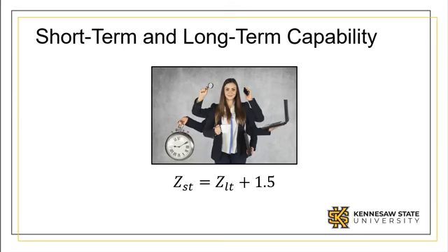Processes are typically assessed based on one operator on one shift, with one piece of equipment and a homogeneous supply of materials. While this is not a realistic state, it will reveal a process state with a smaller degree of variation. As factors for time, multiple operators, various lots of material, environmental changes, and so forth are added, each of these contributes to increasing the process variation.